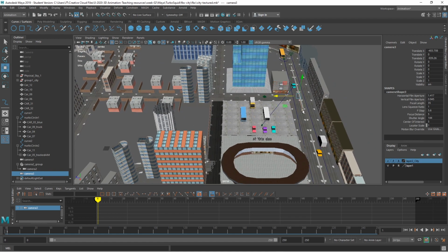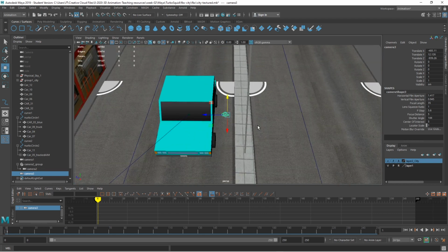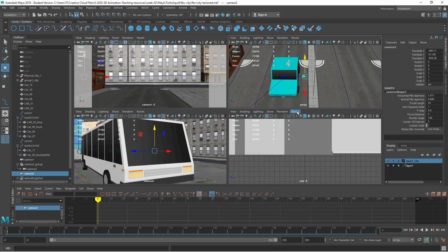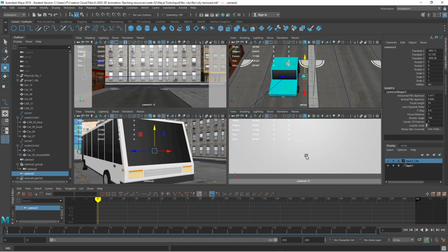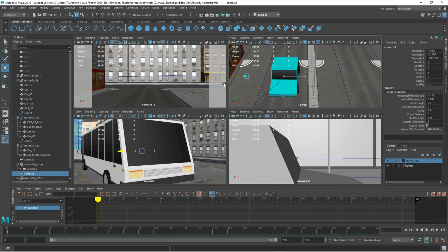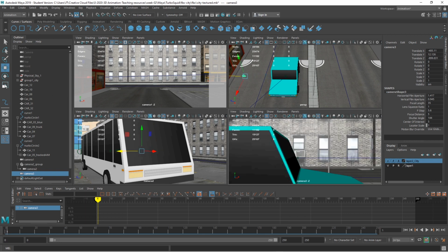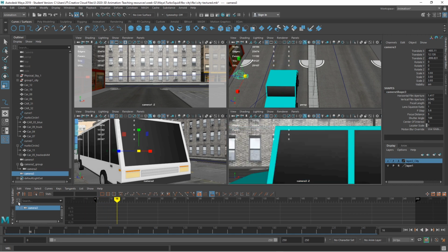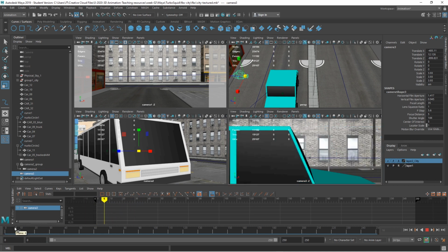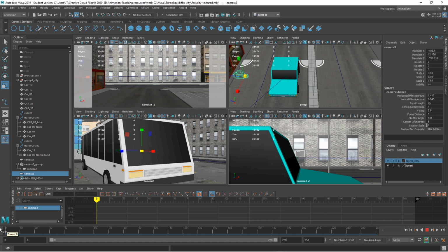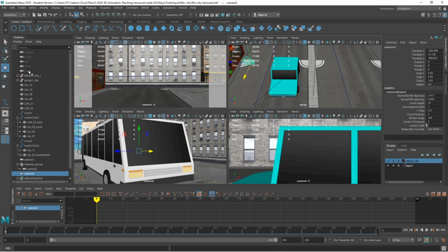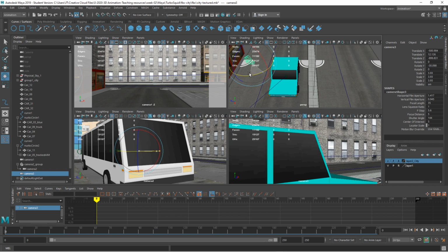And I'm going to bring that camera over to the blue car. So the blue car is becoming a real feature of this. Press space bar. So again, my third camera will be camera 3. Currently it's looking out over there, and I'm going to expand that up. So now I can see at that point that camera, if I'm in this window, that car will drive through the scene. What I might want to do though is have a car cam that will follow with that. So I'll just bring it around the back and just do a few adjustments to this, so I can see where the camera's going.